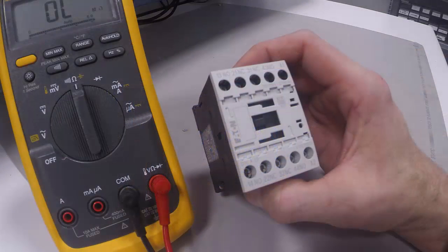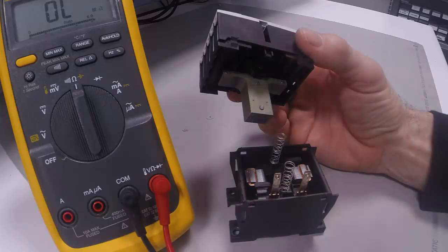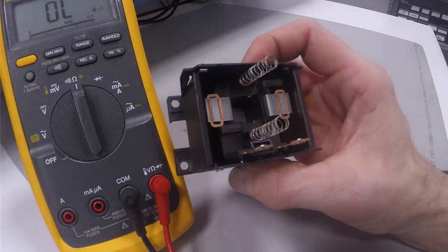One must disassemble a mini contactor relay to see the coil and armature. Upon cracking it open, we see something similar to the internal workings of a contactor. The base carries the stationary portion of the solenoid, the coil, and a pair of return springs that are maddeningly hard to properly realign when you reassemble the relay.